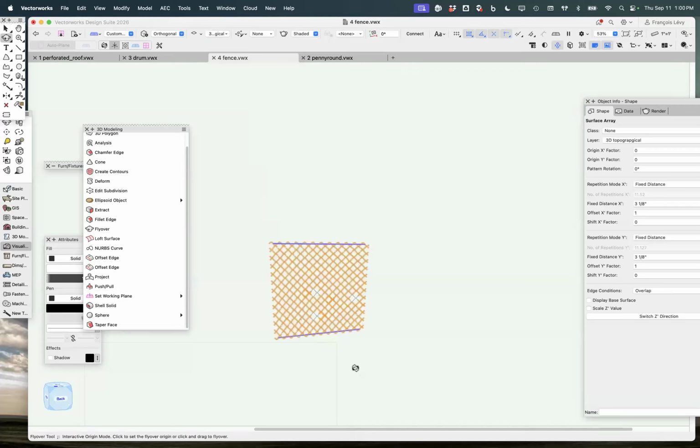You probably want to model your clay tile in a way where you're only modeling the part that's visible, right? Right. You could even go ahead. No, go ahead. No, I was just going to say this is going to destroy the first free afternoon I have. Yeah, you could even just model your roof with the roof tool, right? And then use the Extract 3D tool to just extract each face, and it'll come off as a NURBS, and then boom, you could just throw your tile on there. I think that would work.